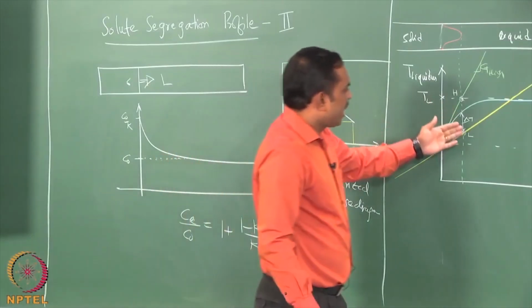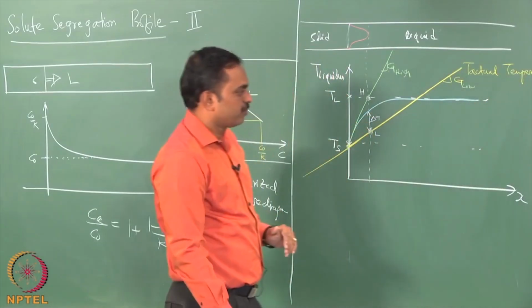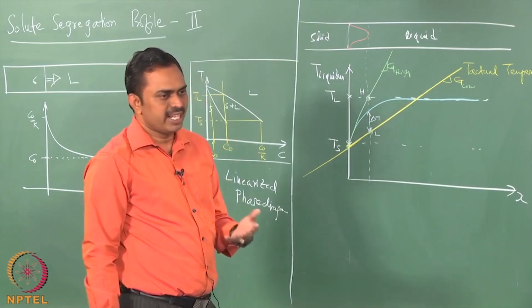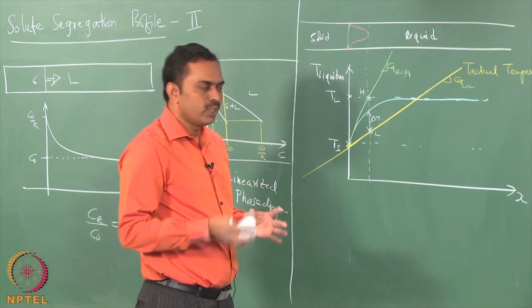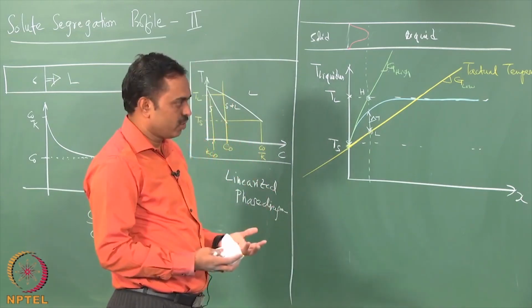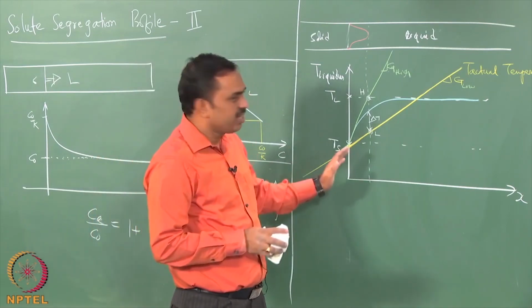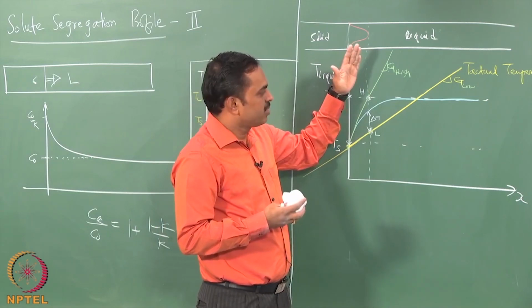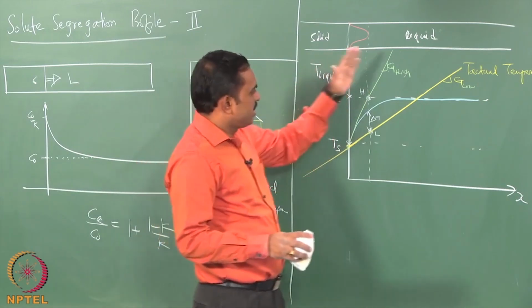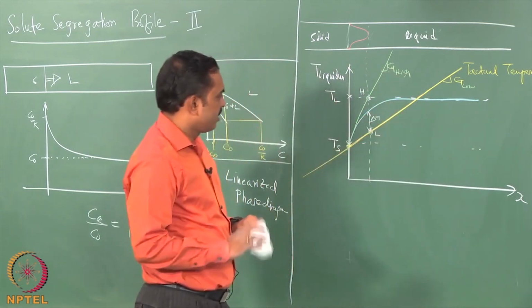So, this is how we can relate the profile with the undercooling, given by the name solute undercooling, with the microstructure that is going to come out. People who have worked in welding would know that electron beam welding usually gives you columnar microstructure in the fusion zone, and in GTAW we normally tend to see an equiaxed microstructure. So, this confirms that in electron beam welding the gradients are very steep, and therefore you get columnar microstructure, and in GTAW or such processes the temperature gradient is not so steep, so you can have undercooling and an equiaxed microstructure can come up.